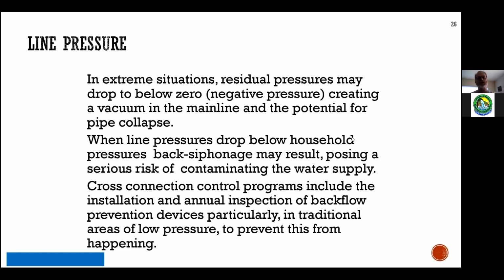The American Water Works Association used to show pictures of a steel transmission main, multiple kilometers long, without sufficient air valves to prevent the vacuum. And steel, by its nature, how it's made, it just flattened and became flat as a pancake. Well, you can't blow it back up. That was a huge, and I can't remember what state it was in. It was like Colorado or something. It was like 40 years ago. But steel water mains will collapse. Vacuum is a potential problem.